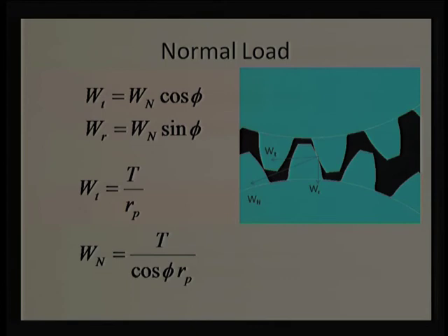Is there any possibility that only one pair is in contact? We know there will be some sort of clearance. If the gear tooth goes into this spacing, to avoid jamming we keep some extra clearance. Naturally, that means when one tooth pair engagement is over, there will be some clearance, and that is going to give a jerk.